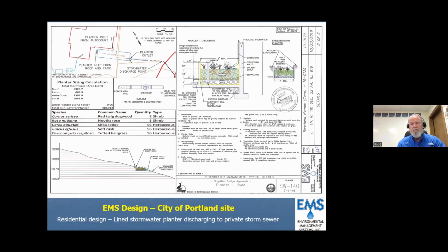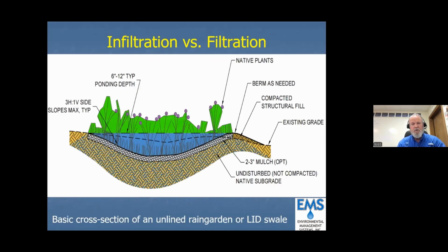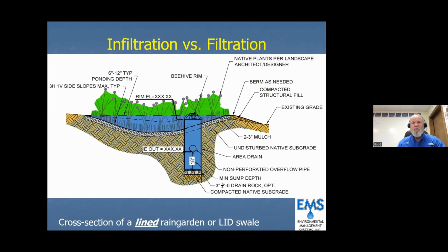Here's another type of system where they've got infiltration through the soil. In this case, your soil and your vegetation is designed to take up the majority, if not all, of the flow. In this case, there is also an added drain. So you've got your infiltration through the swale, but also a filtration and discharge point to drain the pipe, which may go on to another system.